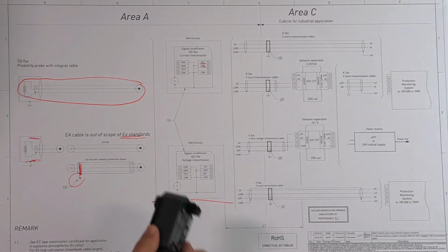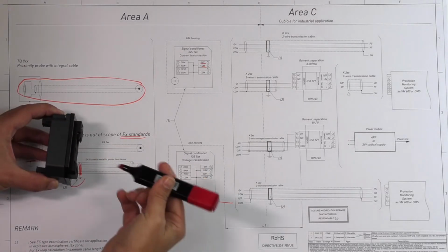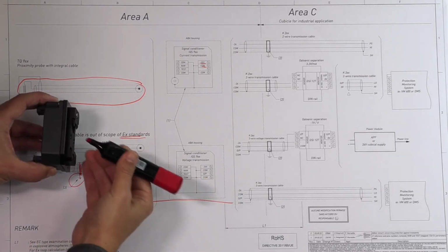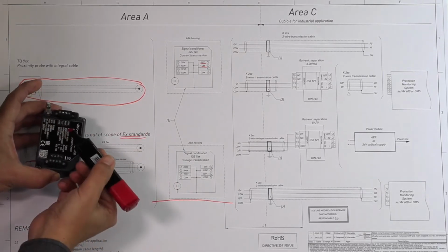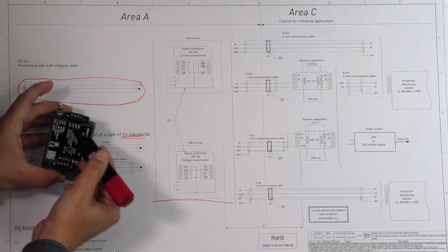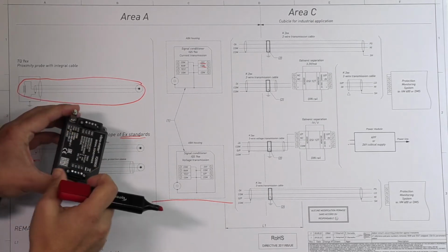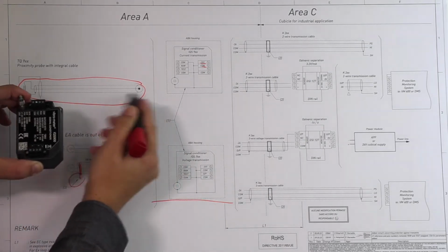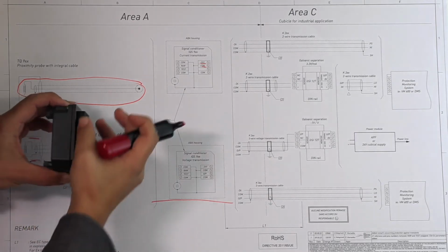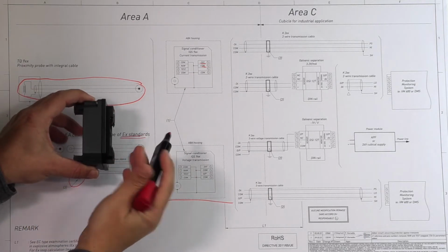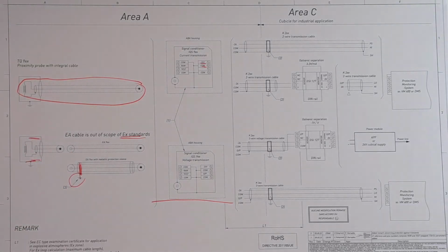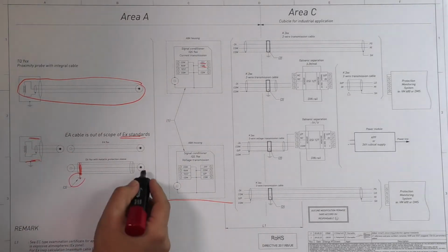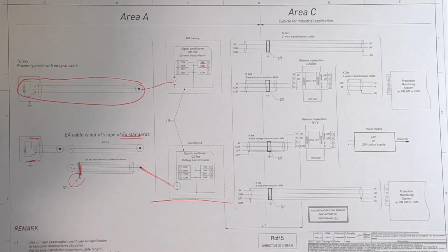We have the option of a DIN adapter that is isolated from the casing. This casing is connected to the COM and also to the shield of the probe. But with this plastic DIN rail adapter, it will be isolated from the DIN rail. So this part should be floating, and you simply connect the sensor to it without any other connection to the ground.